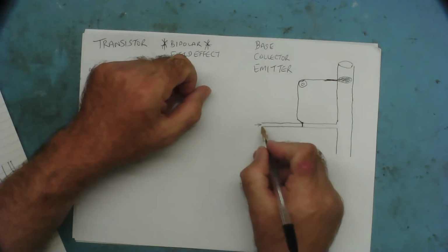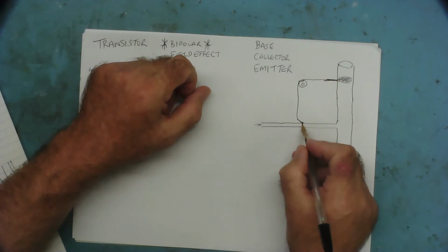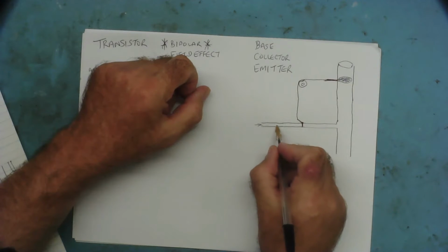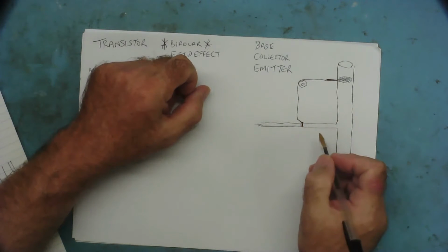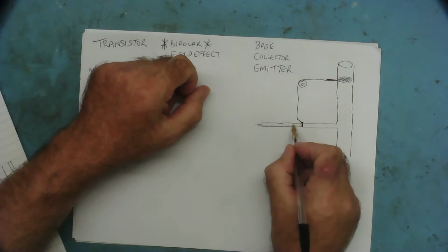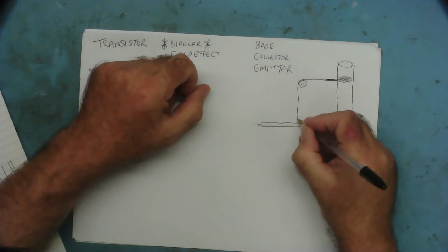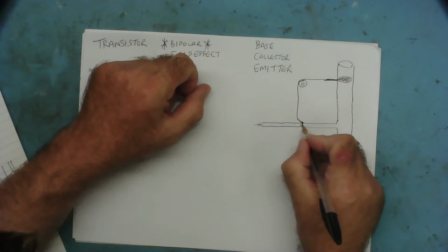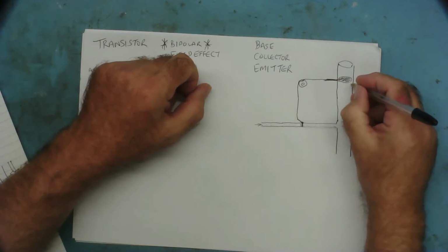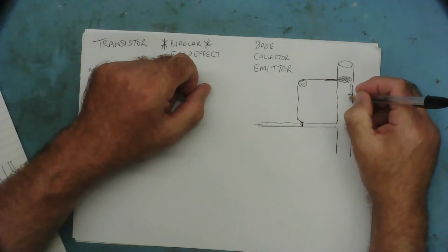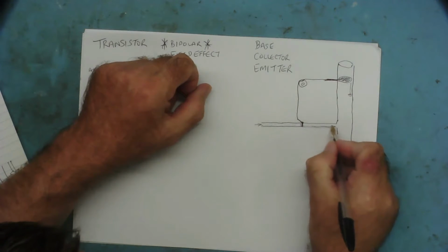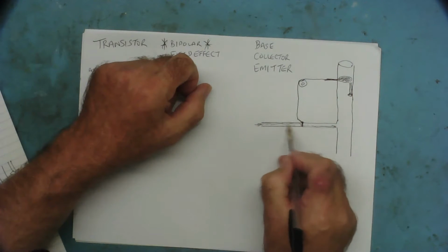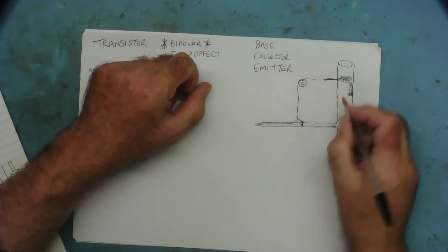So if there's no water flowing down here, then the valve, the flap, is closed, yeah? And when water starts to flow down here, it pushes against this flap. And there's a certain pressure, when there's enough pressure, this starts to open, yeah? So as this opens, the lever pulls on this cable and pulls this one outwards, yeah? So you get a little bit of water coming through here, and you get water coming through here, but you get more coming through because it's a wider pipe. Okay, so if you get a little bit coming this way, you get a proportional amount, but more coming that way, yeah? And as you increase this pressure, this flap pushes further open, so this pulls further down, this pulls further out,